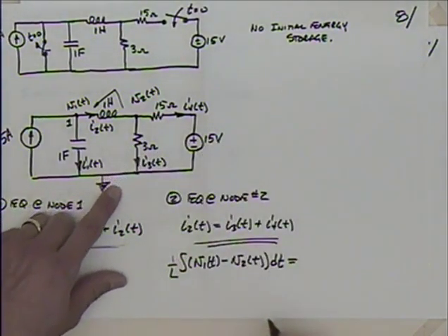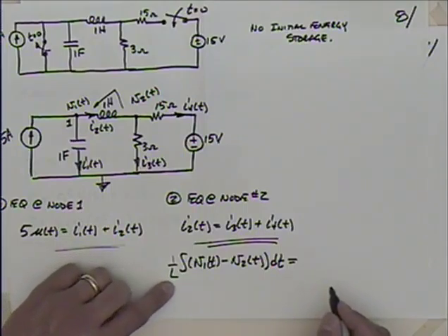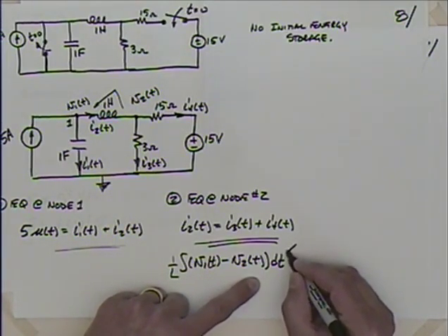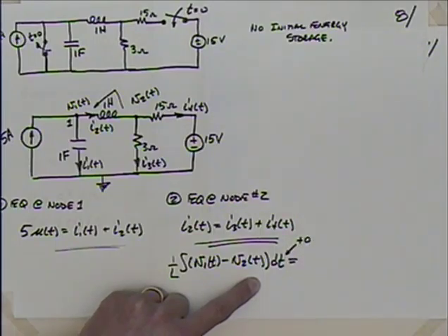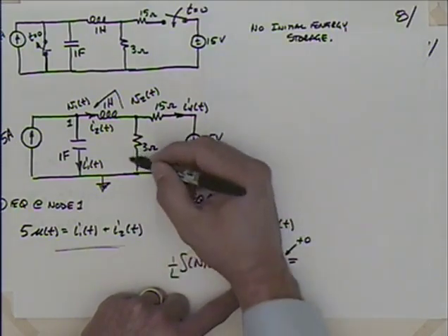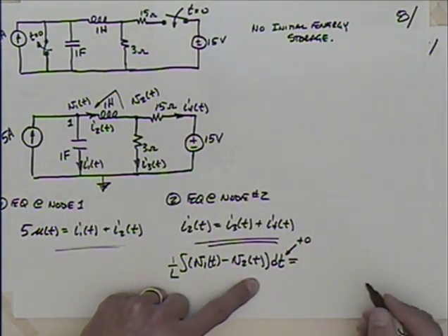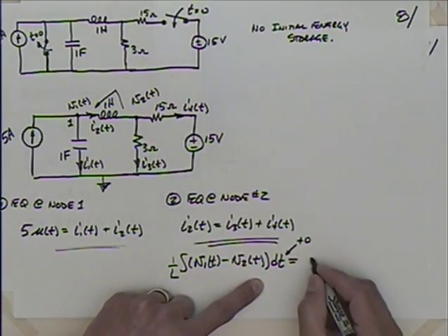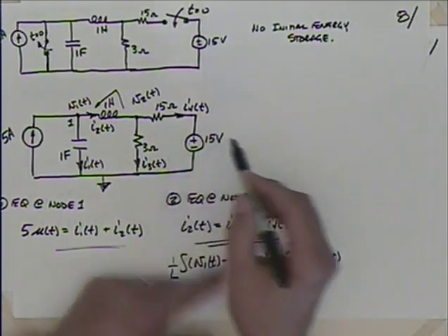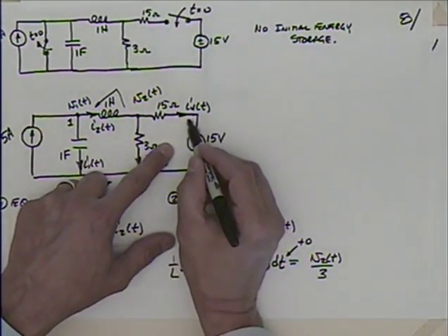That's the current through the resistor, so that should be pretty straightforward. Of course, I should probably put in here plus 0. We'd have that term normally, but we had 0 energy stored. With I3, there's I3 there, which is going to be what? V2 over 3? V2 of t over 3. And then finally I4, that one is a little more difficult.